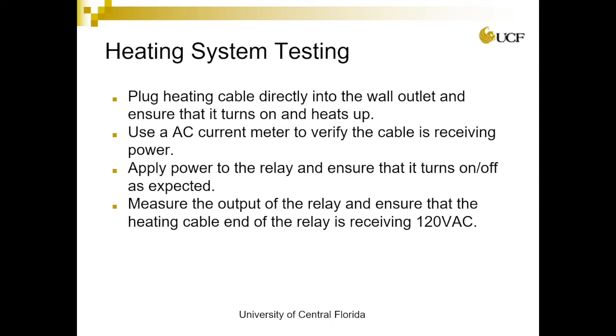We also want to test the relay, so to do that we're going to apply the 5 volt signal to the relay and make sure that it opens and closes as intended, and we're also going to make sure that we're able to get the 120 volt AC power on the other side of the relay.